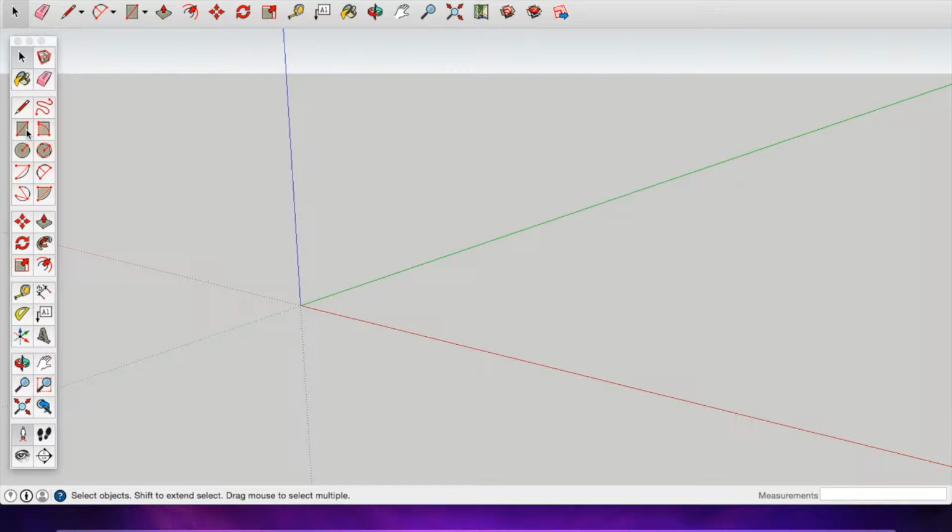I'm going to use the rectangle tool, and I'm going to start at the origin, click, and there's no specific measurements in this assignment. I have a thing that tells me that it's a square here. I'm going to click that there, and I'm going to push-pull this up, and what I'm trying to do is show the thickness of the part you sit on a chair, the seat.